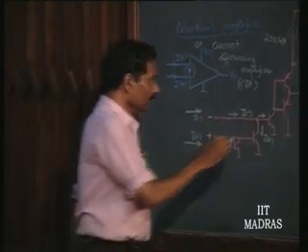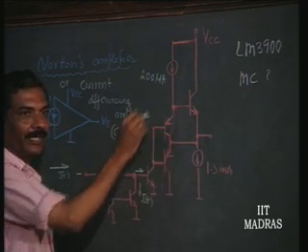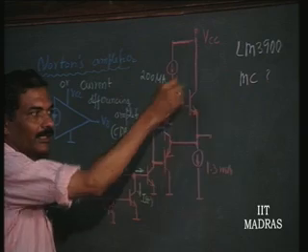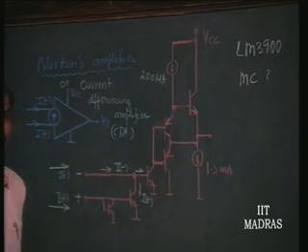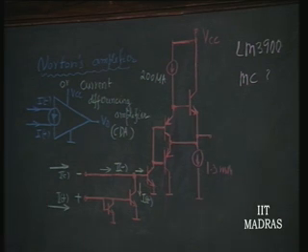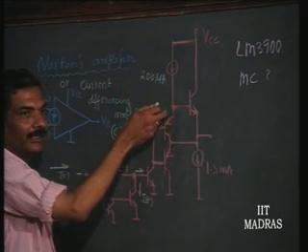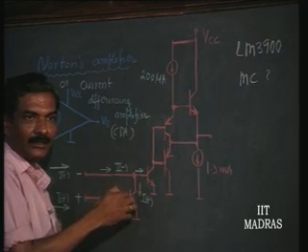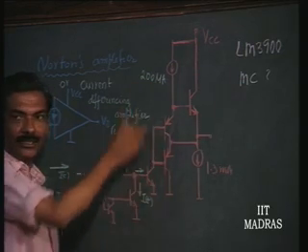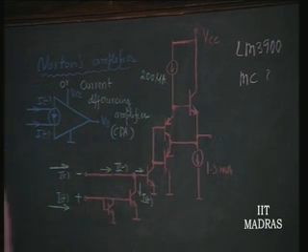So, this current difference is going to be multiplied beta times here and further amplified by further transistor amplifiers, and appearing at the output. This is the output stage, making it appear as an output voltage. So, these are the operating currents of these stages. This is the output stage operating current, this is the intermediate stage operating current. So, it also has a current differencing input stage, an intermediate stage, and an output stage. So, you can see the 3 stages again appearing in this operational amplifier.